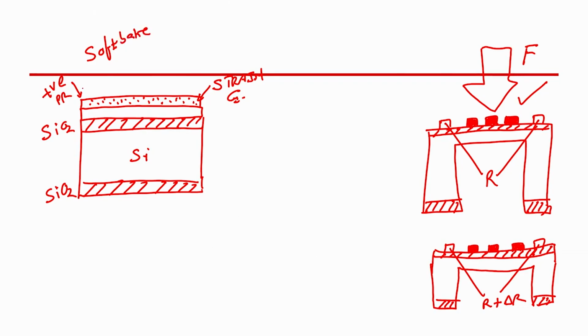Right. Next step would be loading a mask. Mask would be a bright field mask, right, bright field mask. So, the region of the photoresist which is not exposed will get stronger, right. We have already studied that when we take positive photoresist, the area which is not exposed will get stronger. What is this? This is my bright field mask, right. Next step would be